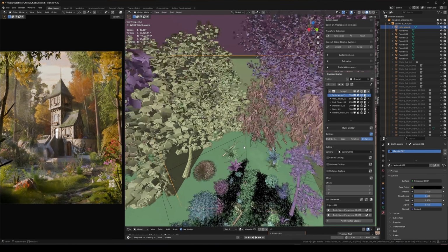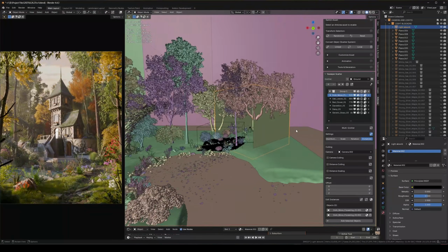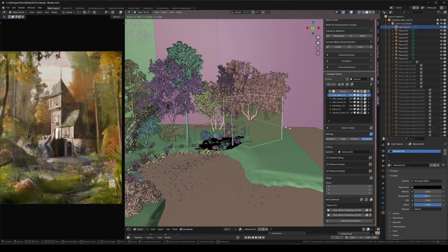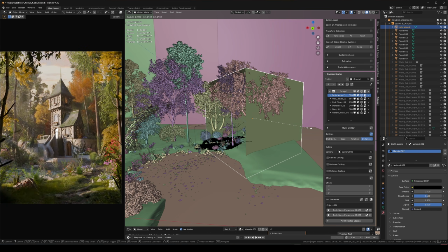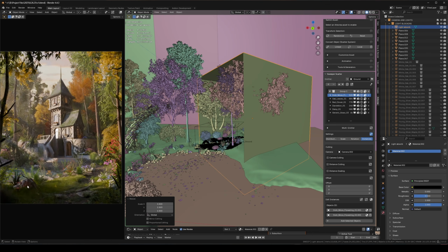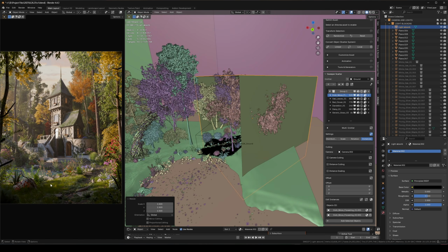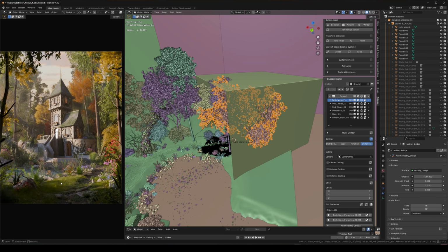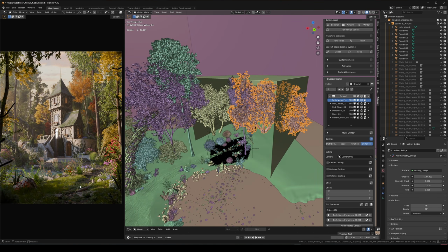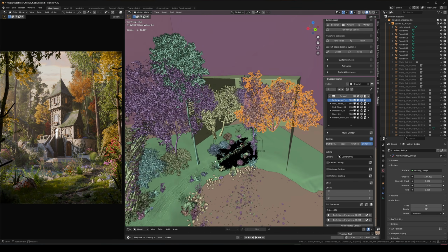So my method when I'm placing these is basically I scale up the cube until it starts blocking the amount of area that I like. I usually don't want to see this hard cut. As you can see, right here, there's this hard cut from the cube. I don't want to usually see that. It sometimes works. If I do have it visible like this, I'll try to blend it with these trees just to create more natural shadows around the edges of the cube, just so it doesn't have this straight line between light and then shadow. You can kind of break it up with these patches.